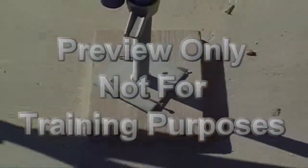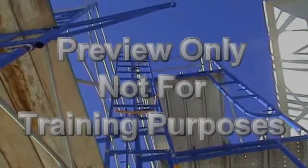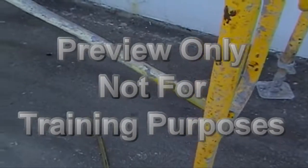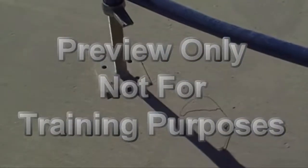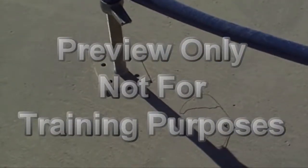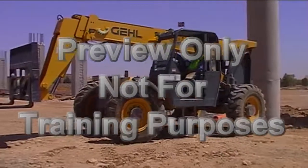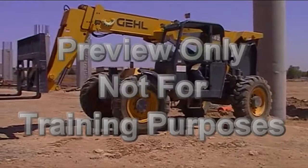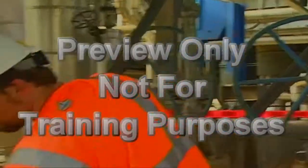Scaffolding must be built on a stable base foundation. It must be square and level. Set all scaffolds on base plates, mud sills, or another adequate firm foundation. Footings must be capable of supporting the loaded scaffold. Front-end loaders and forklifts should not be used to support scaffolds unless specifically designed for such use by the manufacturer and permitted by the qualified person on the job site.